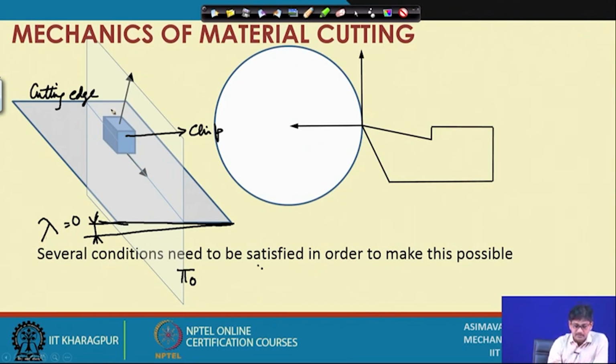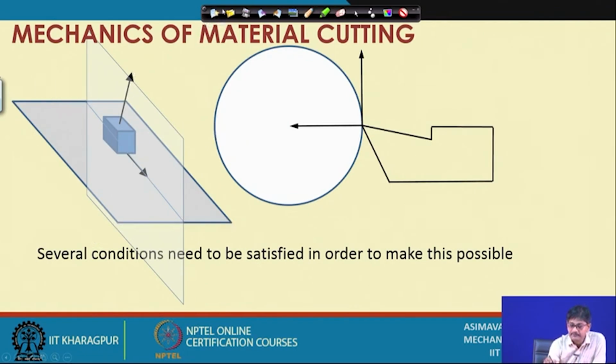See, the cutting edge is not supposed to have any inclination, so this is 0, and in that case this is the orthogonal plane. The forces on the chip will be totally confined to the orthogonal plane. Frictional force, which the chip applies on the rake surface, and normal force, which exists as normal reaction between the chip and the rake surface. So, this is the normal force, and they are totally on the orthogonal plane. So, having agreed about that,